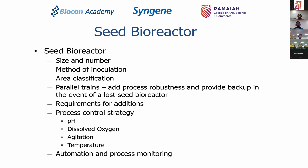You have to have a process control strategy: the pH, the dissolved oxygen, the type of agitation that you use, the temperature at which you are doing it, and what kind of automation and process monitoring you are doing at each stage of this growth. It is less on the wave bioreactors, because they are very simple equipment.